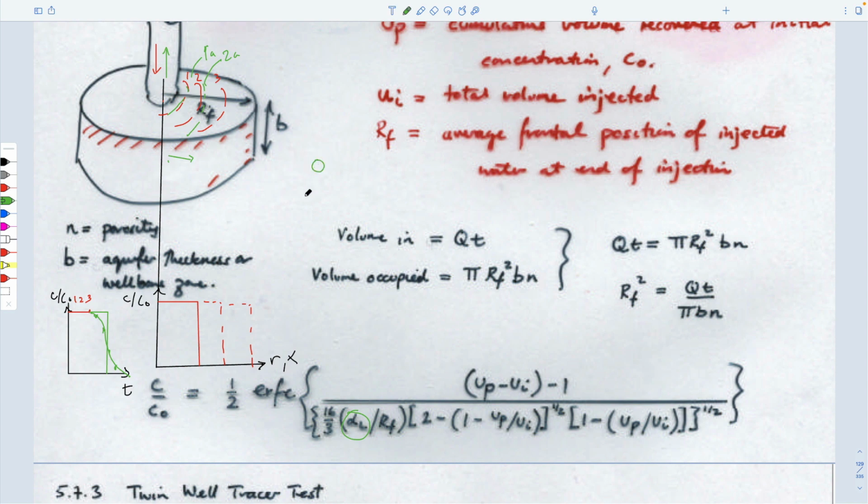And so if you think of looking at this in plan view, and you think about the streamlines that you'd have, we talked about flow nets, I guess, in a prior life. A flow net that would represent this behavior would look exactly like this. These would be lines of equipotential, equal pressure head, because you're driving flow. These would be individual lines that the individual water particles and contaminants would take, on these rays.